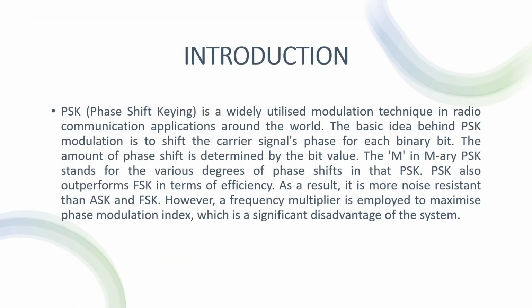Starting from the introduction, PSK, or phase shift keying, is a widely utilized modulation technique in radio communication applications around the world. So basically the idea behind PSK modulation is to shift the carrier signal's phase for each binary bit. The amount of phase shift is determined by the bit value. The M in M-ary PSK stands for the various degrees of phase shifts in that PSK. So the degree of phase shift can be multiple according to the M, or modulation.